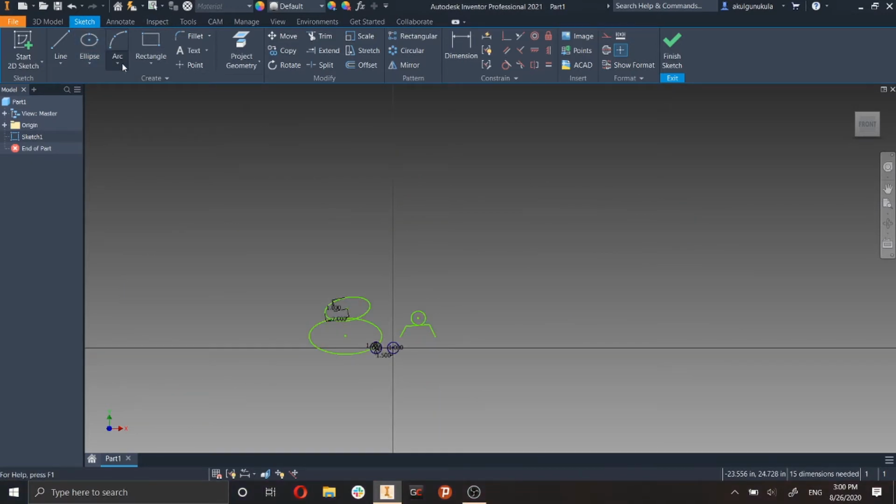So now let's talk about the arc tab. There are 3 different ways to make arcs. Different scenarios require different things. So let's talk about the simplest one, the bottom tool, arc to center point. The first point you are supposed to select is the center point, same as the center point circle. And then let's type in what we want the radius to be first.